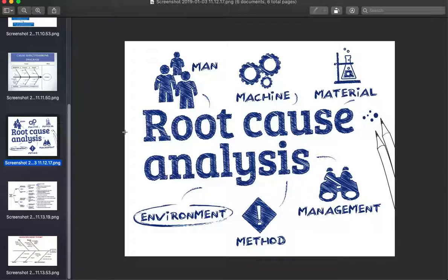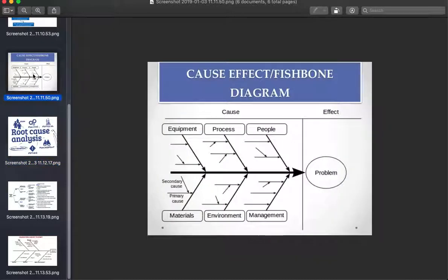Start making notes. One for me in the printing industry was to use something like a fishbone diagram, because there are different systems in the machine. And so starting to understand which system was breaking down. Was it a diffuser? Was it a graphics issue? Was it a sensor? Was it an interlock? Was it a stuck relay? And starting to understand which of this equipment was breaking down, and then cutting those in half and starting to weed those things out. And again, like I said, something can be a symptom and be disguised as a root cause, and that happened a lot. If you get a printer jam and it says it jammed at the 45th foot of the printer, but the root cause was really back at the feeder.